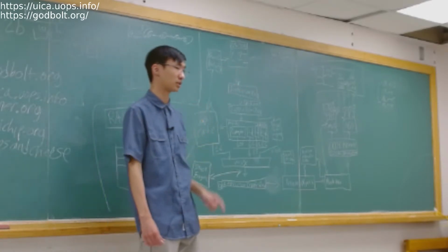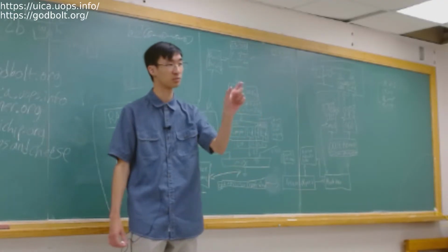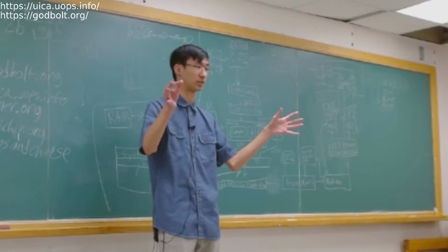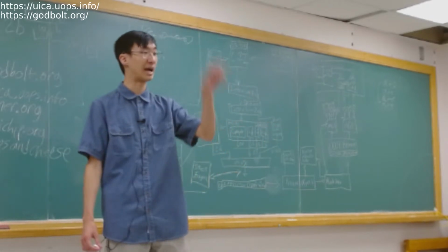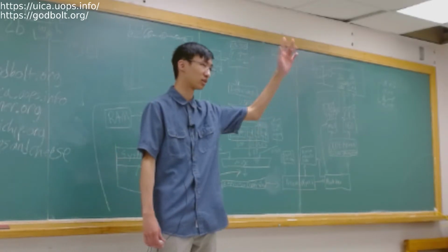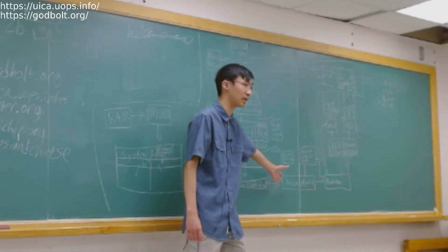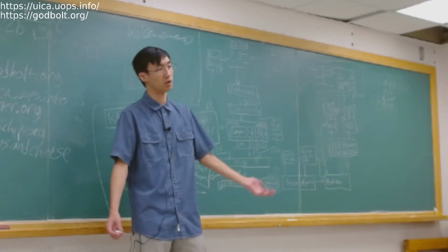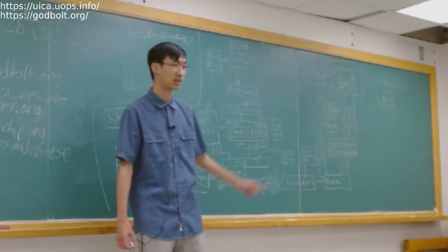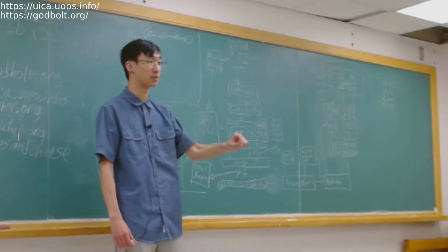That's move elimination. The other thing is that there are some common ways to create zeros or ones inside of your registers. For example, XOR register with register. If you take XOR 1, 1, then you get 0. 0, 0 is 0. Obviously, that makes all zeros. So if you hit this stage in the pipe, you go, well, I know it's 0, so I'm not going to calculate it at all. I'm just going to make a 0. Same thing for ones. That's very common when we want to do things like remove dependencies.